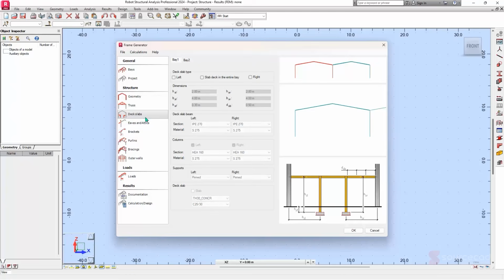The next item is about the deck slabs. In the event that, let's say we want to place an office, we can specify that we want to place it on the left hand side. We can clearly see that it has been added here, not only in one bay, because it's mirrored or symmetrical or identical to the other, it's also added on this other side. So we can specify the HSL, which depicts the left, which is basically the height from the top of the foundation all the way to the top of the slab.